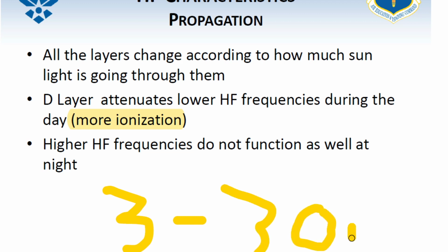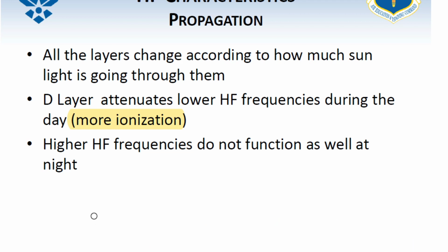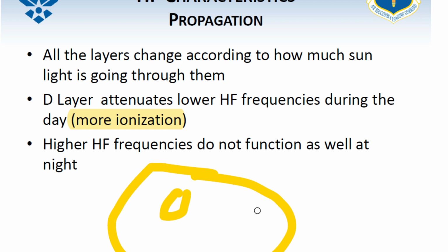Yeah, you want to use like 29 maybe? 29, I like it. And why is that? Because the sun would be near its highest point, but not quite. Yeah, so the sun's up. So you want to use a stronger frequency so that you can effectively use the ionosphere for your beyond the line of sight communication.